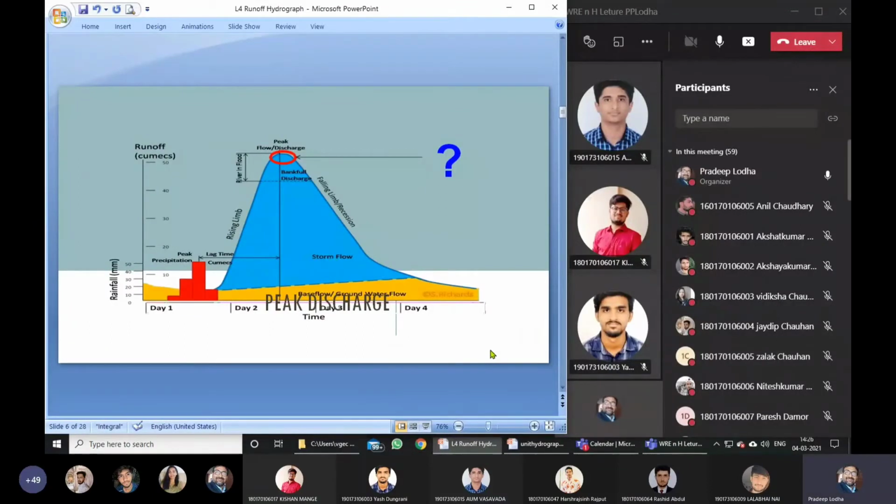This is another sketch of the hydrograph. This is also not a unit hydrograph. Another sketch to understand more detailing of the hydrograph. Again, you could see this is rainfall, drawn as a hyetograph. There are two curves combined here, because we need a hyetograph to draw the hydrograph. Because the hydrograph carries surface runoff, we draw the hyetograph for the sake of drawing the hydrograph.